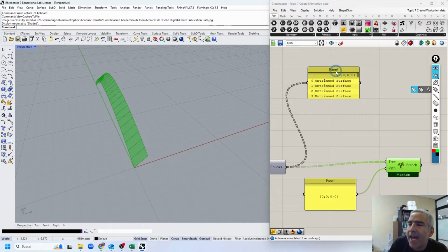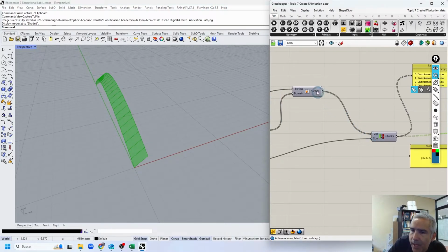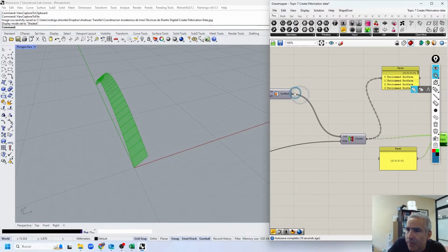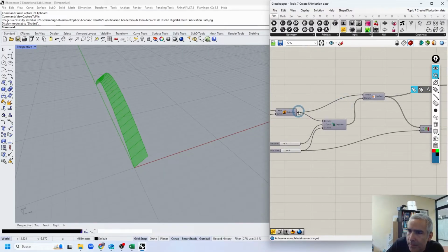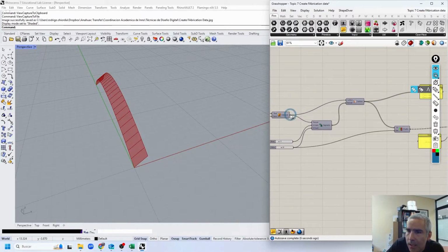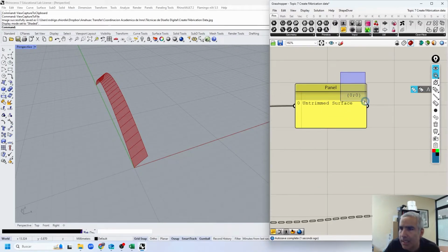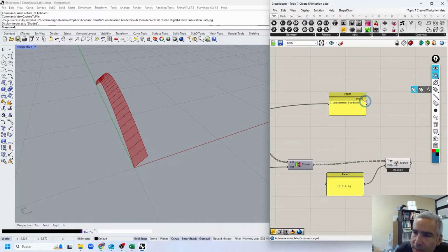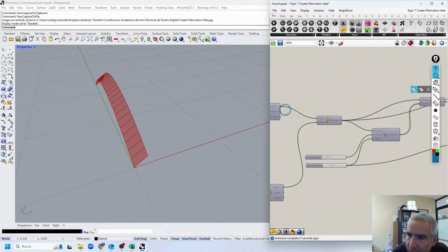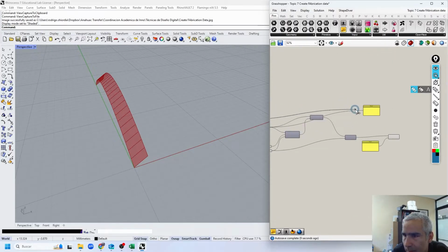And in these paths, you have a bunch of zeros just because you have a bunch of steps before. You can see that this list has 3 zeros as the branch path. And Grasshopper will aggregate these, like as you can see, in the previous step you have only 2 zeros on the branch path, even though it's a list with a single element.